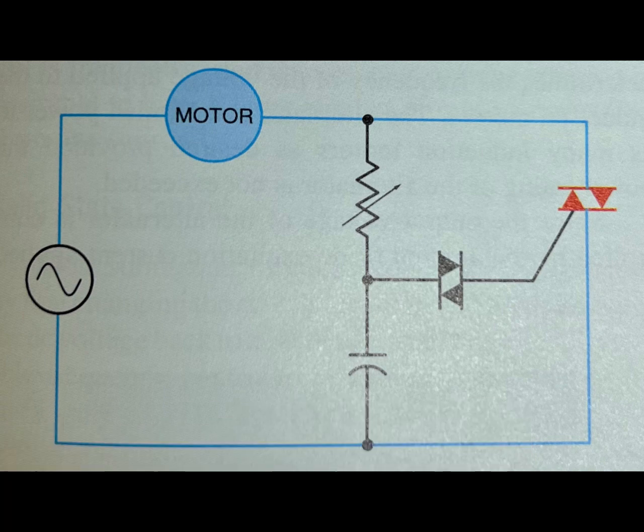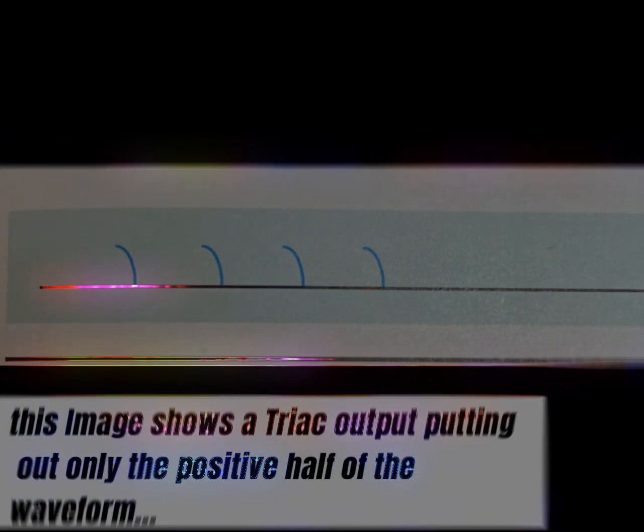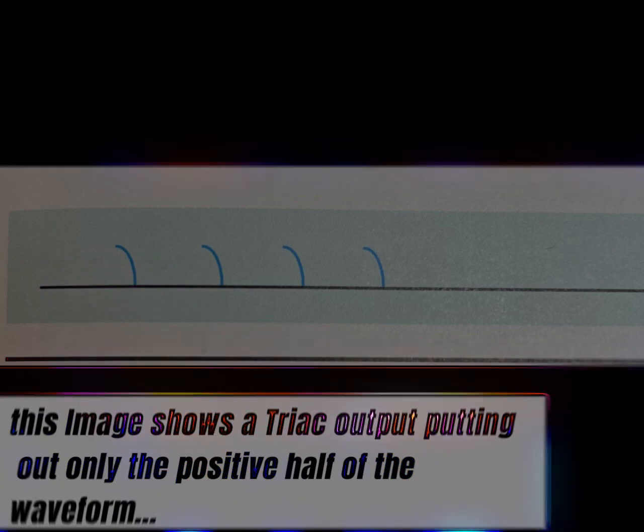Two factors that determine the speed of the rotating magnetic field of an AC induction motor are: first, number of stator poles; second, frequency. If either of these factors is changed, the speed of the motor can be changed. The speed of a consequent pole motor can be changed by changing the number of stator poles. This method of speed control causes the speed to change in steps and does not allow control over a wide range of speed.